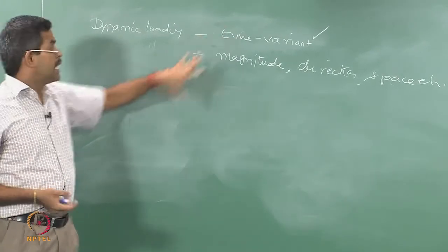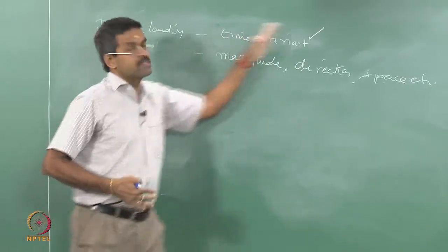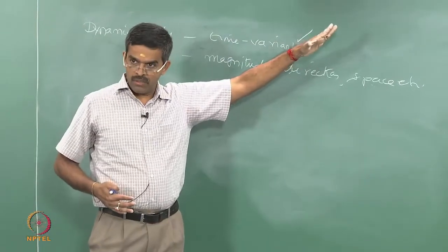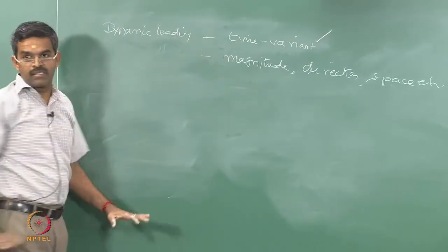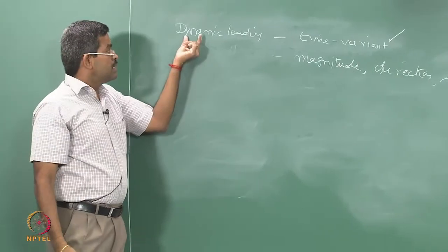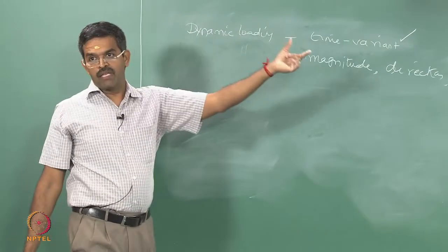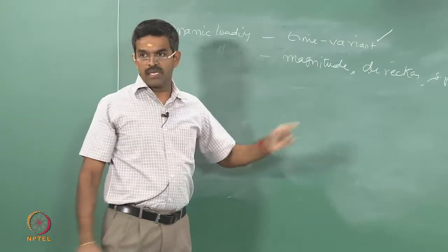Now, the question comes, any load which has a very low magnitude but varies with time, can it be called dynamic loading? The loading can be called dynamic loading, but you need not do a dynamic analysis. Why? The most important component to do a dynamic analysis is the inertia force.